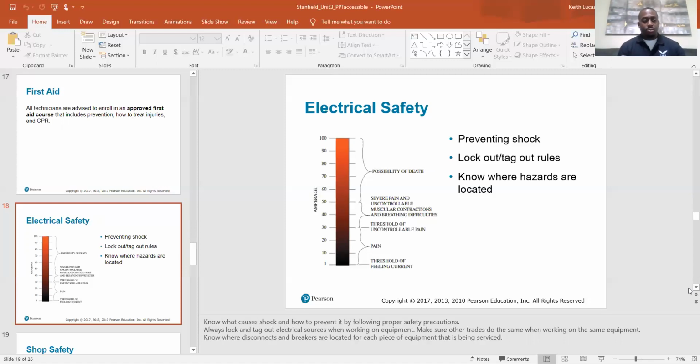So let's say 4 guys are working on the same thing. You've got 4 padlocks on this one lockout tagout. That means when one of the 4 guys is done with their work, they still can't just flip the switch back on and walk away, because 3 other guys are still working on that machinery. It's protecting all the other guys, because if one dude finishes and flips the power back on without realizing someone else is still working on it, he could injure that person. So that's how the lockout tagout system works.